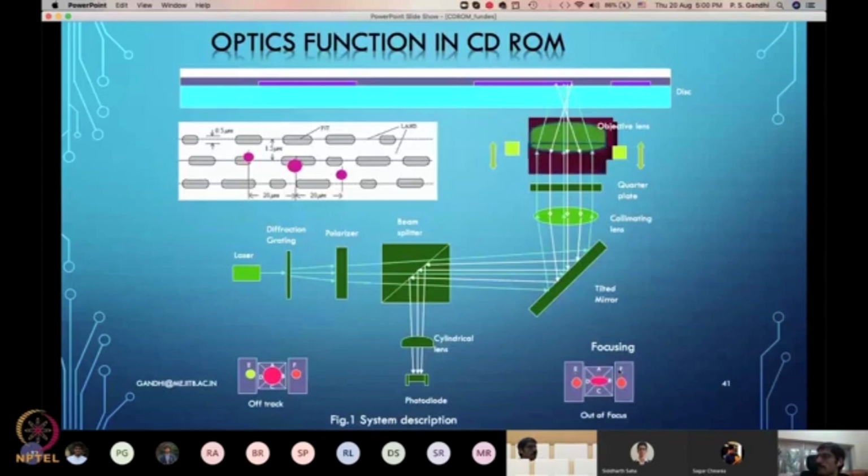Yeah. So focusing on one side, it is covering like that, and in the other defocus direction, it will go in the A and C direction. So if I consider this signal A plus C minus B plus D, then it will have an error signal covered up there. Okay, and that's how I can detect whether it is in focus or it has gone out of focus. So is that part clear? Is there any question about this part again?